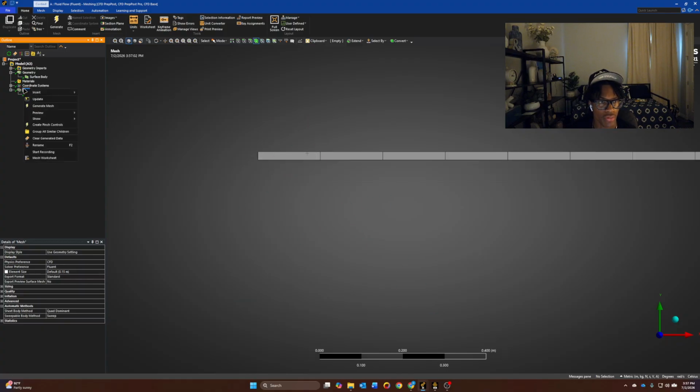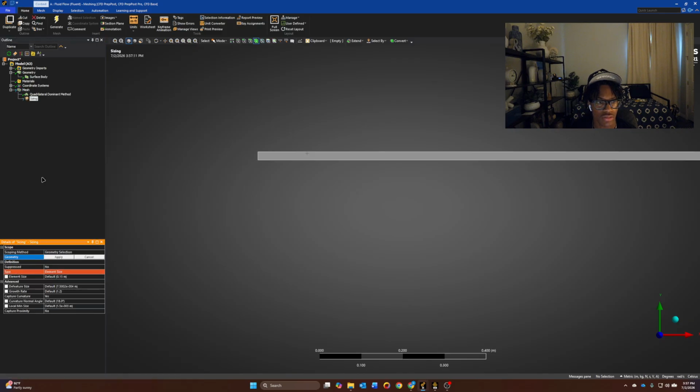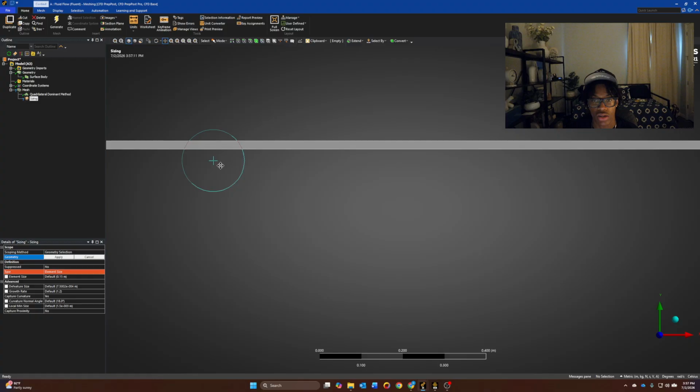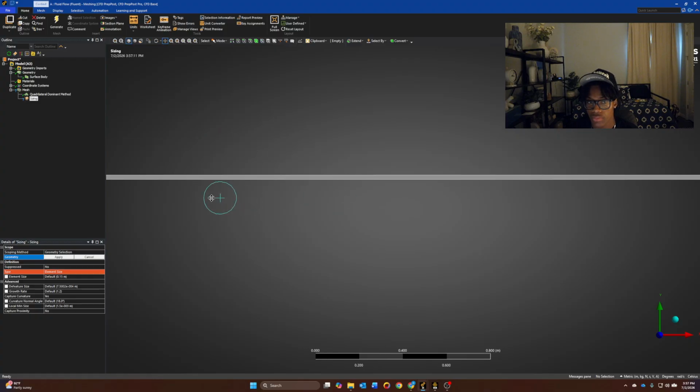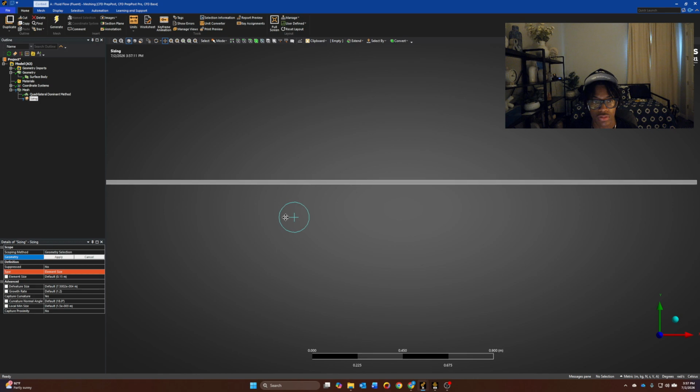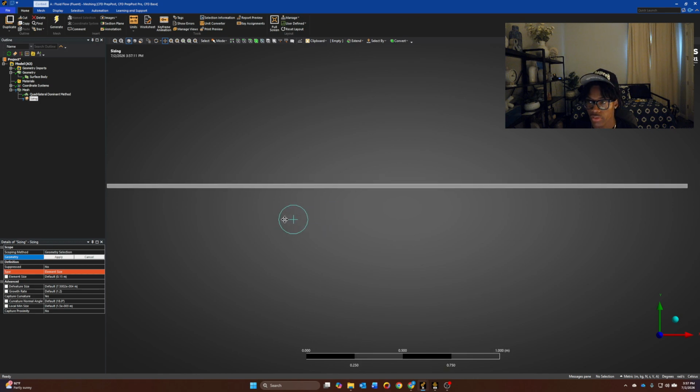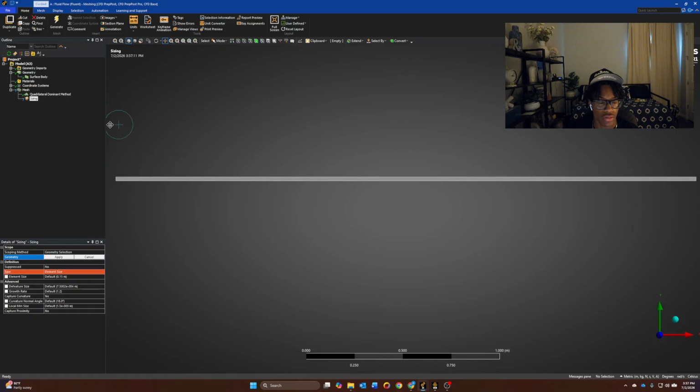and then we're gonna do another mesh, and we're gonna do sizing. And then for this, we're going to do the edges, the inlet and the outlet. So I'm going to resize this to fit the screen first so that I can capture both at the same time. That is a lot more. And what we're going to do is select the edge tool and hit Control. We're going to capture the inlet and the outlet. And we're going to apply the geometry.